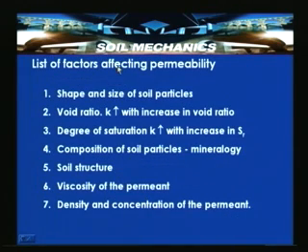So, the list of factors affecting permeability can be listed like this. One is the shape and size of the soil particles, and the void ratio. As void ratio increases, k value increases. That means soil with higher void ratios can have higher permeability. Then the degree of saturation: k increases with increase in degree of saturation. Partially saturated soil, because of the entrapped air within the voids, can have low permeability.